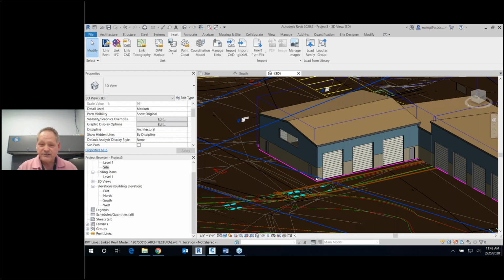And then bring that into the architecture model. You're going to be able to drop it in on shared coordinates now, right? When you export your model to CAD, you're going to export it using shared coordinates. You can drop that into the architectural model. So sure, yeah, I'm sorry, you can export that into the site model. But yeah, I'll have a version of this definitely in that architectural model. You know, we'll bring in the topo, we'll bring in all those elements.